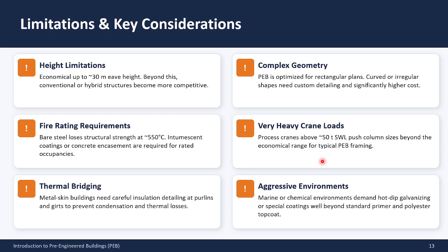PEB has its limitations also, and it's very important to know them. It is economical only up to about 30 meters eave height. It works best for rectangular plans. The complex geometry adds cost.